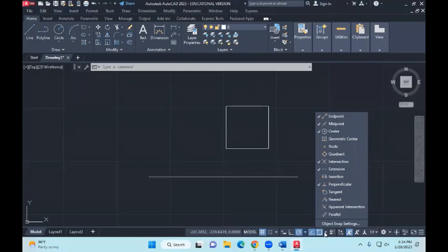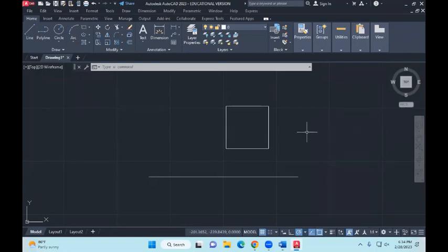Okay. So AutoCAD will automate this. If you draw a line and you do not know the length of the line, AutoCAD will automatically give you the endpoints of the line. AutoCAD will automatically give you the midpoint of the line. Got it? I think in your case, midpoint will not be selected, so you select midpoint. Let's just draw a circle, circle, enter. So how do you find the midpoint?